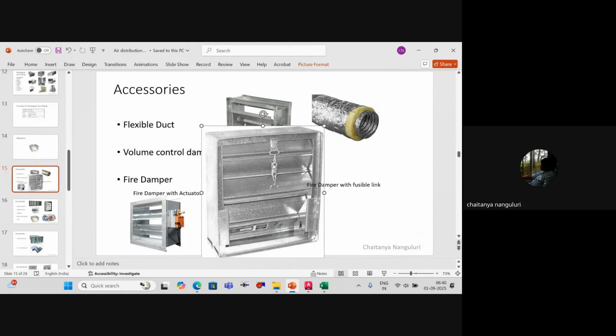You can see a kind of a latch over here. This is made of a material like galvanum or anything which can basically melt at 50 degrees. What will happen is you have a spring loaded here. You will open this louvers and hook it to one of the louvers. One of the louvers will have a small projection, which is not clearly visible here. So you will latch it to that gate.